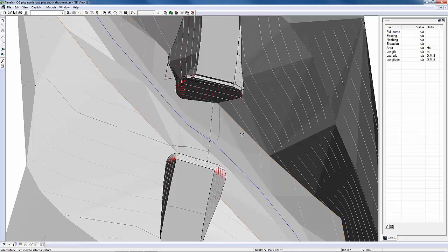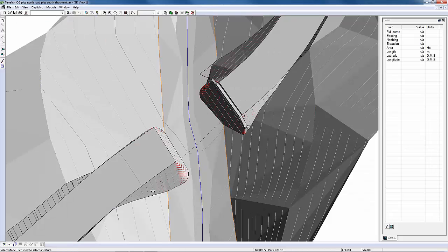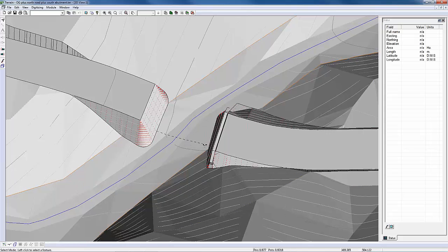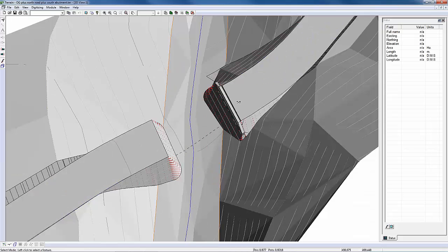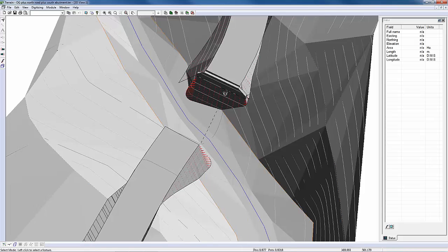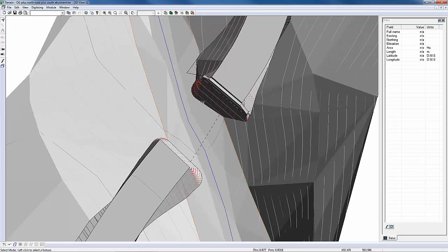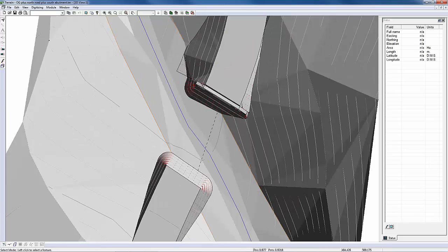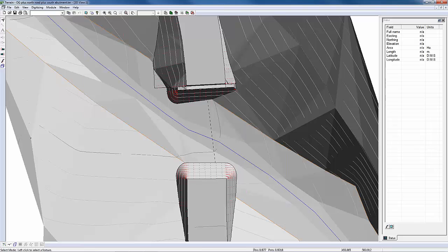So this is the simplified version in the north. Just no wall, just using the road edge features just to grade down to the ground. And this is the more advanced bridge design with a ballast and grading down to the ground. Abutments and ballast, and then merging the existing road and making sure that existing road gets as close to that abutment as possible.